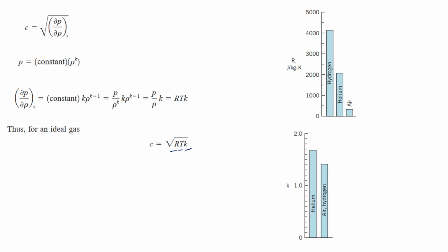We can also look at it by using another term, and that is the bulk modulus. Bulk modulus deals with the compressibility of fluids, that is, if we change the pressure, what happens to the volume of a certain fluid. But here we will not be talking about the volume, we will be talking about the density: by changing the pressure, what happens to the change in density. So let's look at this, that is the definition of the bulk modulus, that a change in pressure results in the change in density from rho to d rho.